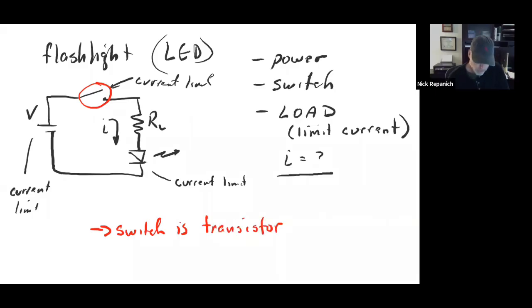So voltage supply, yeah, you're going to do that. The switch in the LED is going to be a transistor instead of a physical switch. Okay. And then you've got some sort of resistance to limit the current. The whole purpose of all of this is to turn on the light, an LED, right? That's so that you get light out of it. So you run a bunch of current and you size all the devices, I equals. Really easy circuit, isn't it?